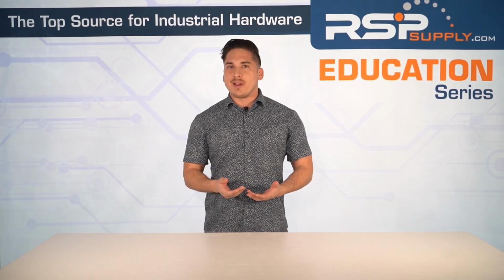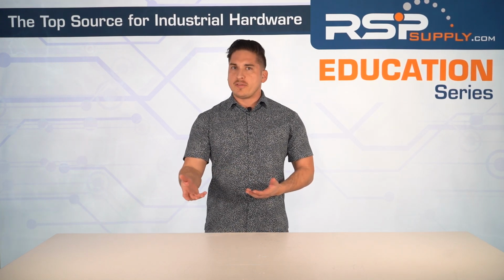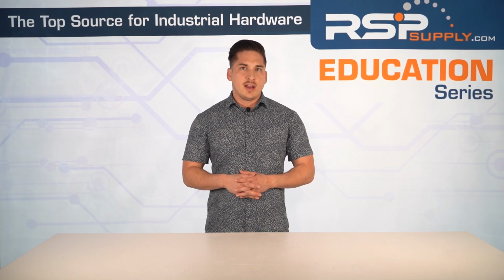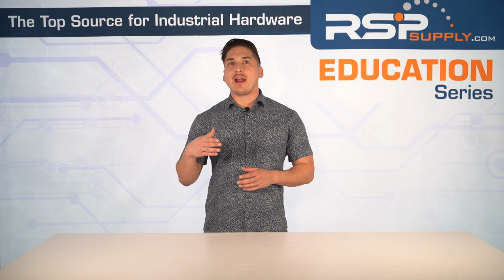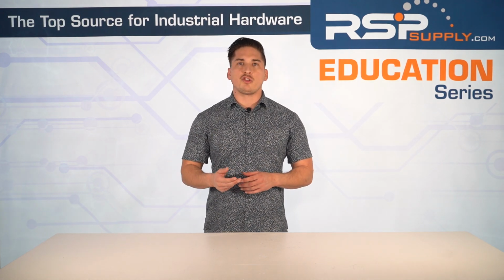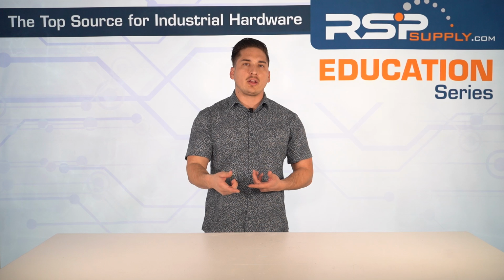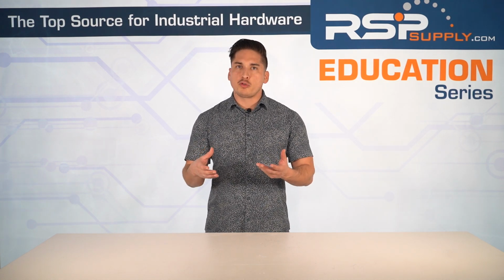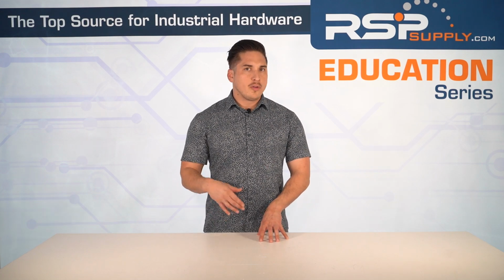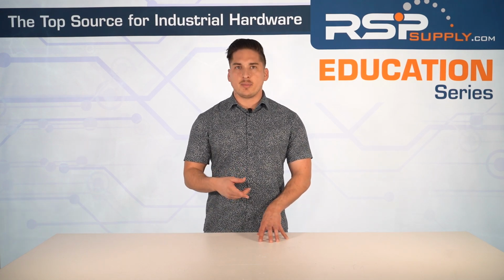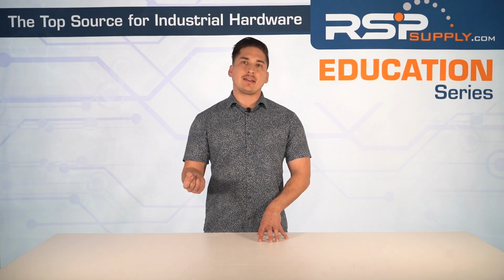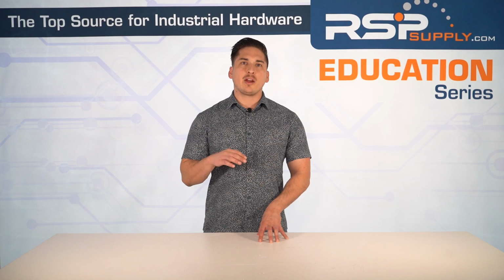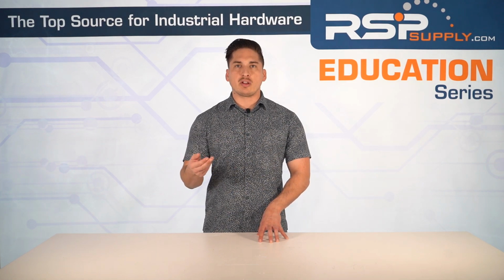This sinusoidal waveform is characterized by its frequency, typically 50 hertz or 60 hertz, 60 hertz here in the US in industrial settings. Its peak voltage, and importantly, its RMS, or its root mean square voltage, which represents the effective voltage value for power calculations. Understanding RMS versus peak is crucial for component selection and system safety. Furthermore, polyphase AC systems, typically three-phase, are prevalent in industry. They offer smoother power delivery, higher efficiency for motors, and reduced torque ripple compared to single-phase AC.